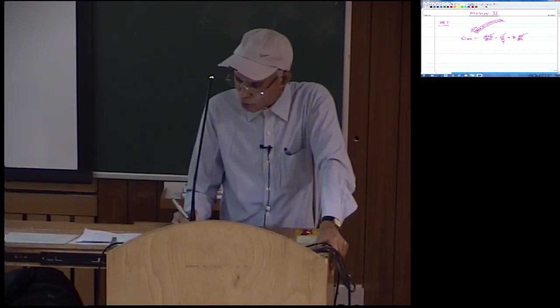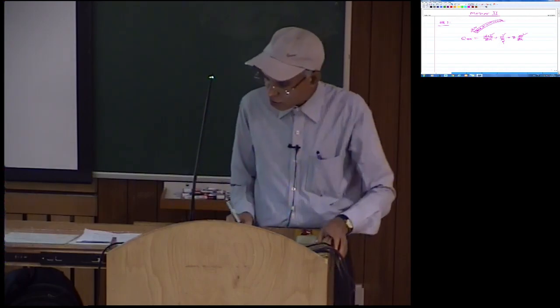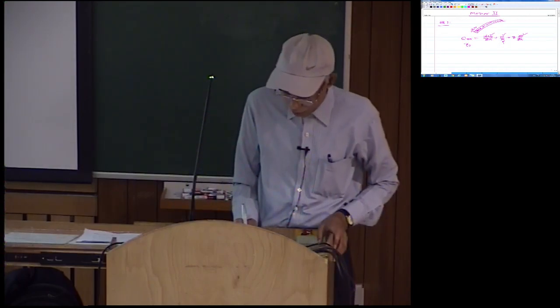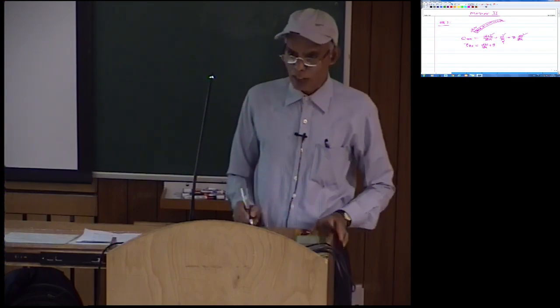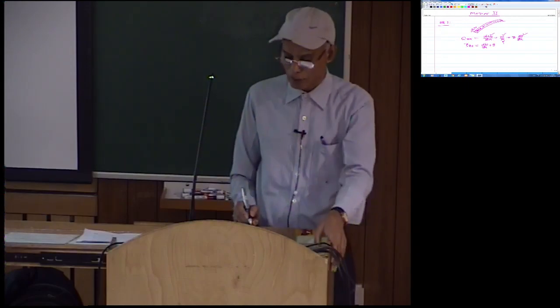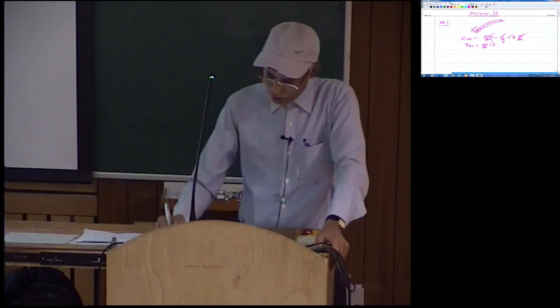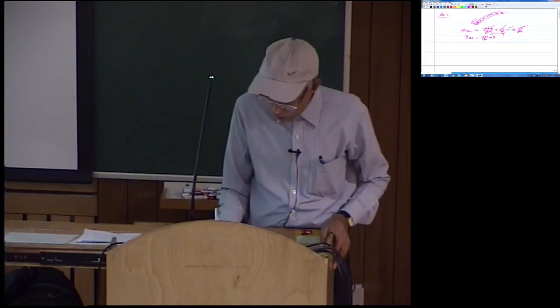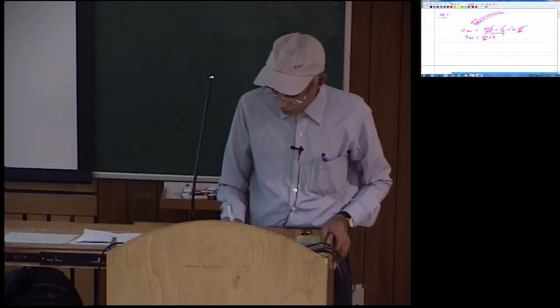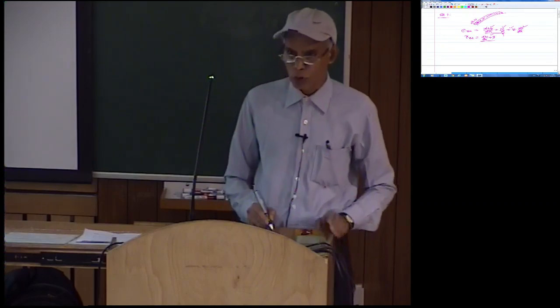Thin and shallow beam elements depict membrane and shear locking. In addition, you also have the shear strain gamma xz given by dw by dx plus theta. Here theta is the rotation about the negative y axis, so that is why you see a plus sign here and similarly a plus sign there. Membrane locking arises because of this term which I had mentioned, and since I had discussed shear locking in class, I left that for you to interpret.